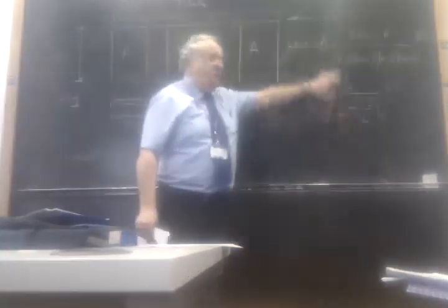This often seems to be a place where people get sort of mixed up. They're used to saying EI over L and that sort of thing, and then they come to look at a problem like this, they get a bit mixed up by what's L. Is L that? Or is that L for wall A? It's 1200 plus half of that.